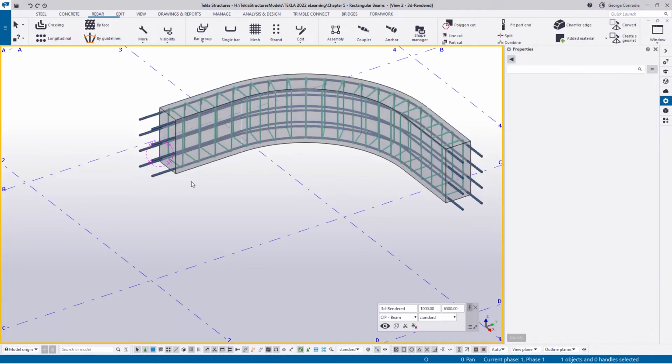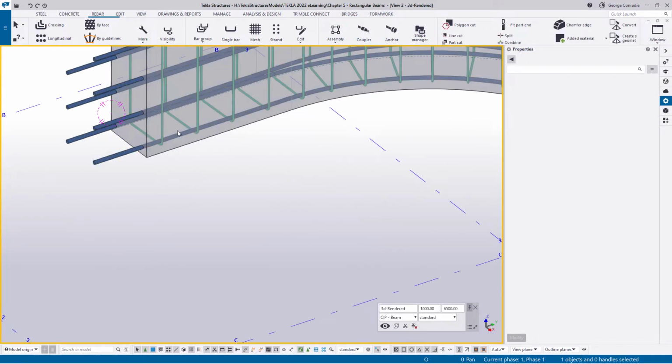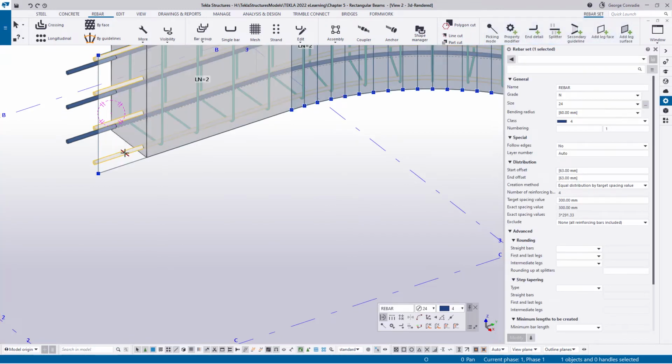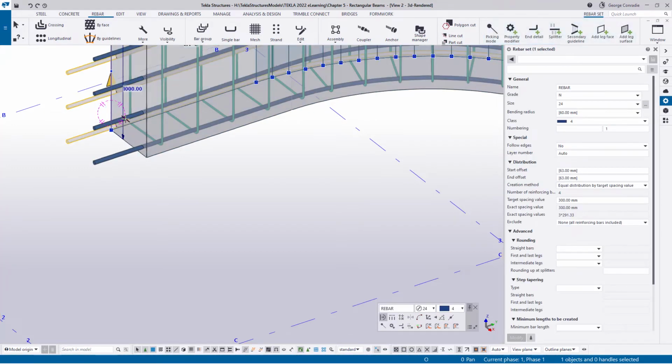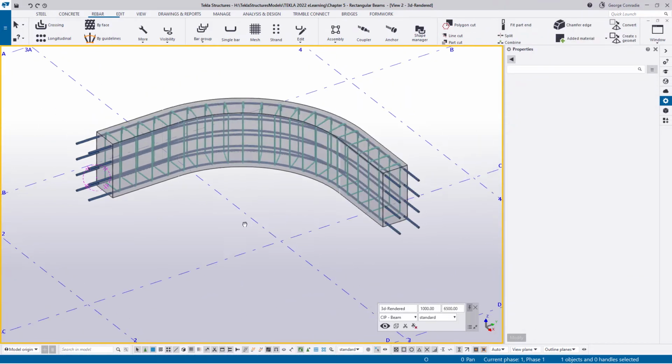Now, the difference between the two is if you want to put a splitter on this bar that's got the extended face and it's got a crank, it's got enough room to work with to actually calculate the crank. Whereas on that one, it's going to use the face and it's not going to be able to put in a crank that we want because there's not enough bar. It's going to give you an error. So let's see how that works.